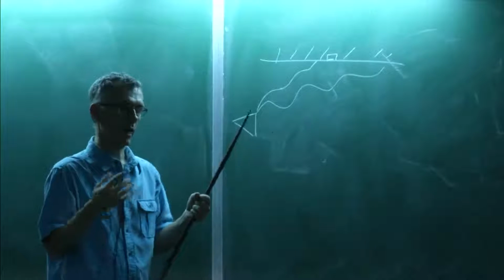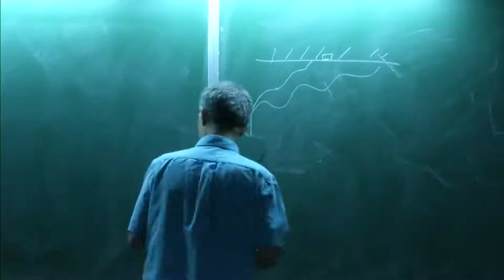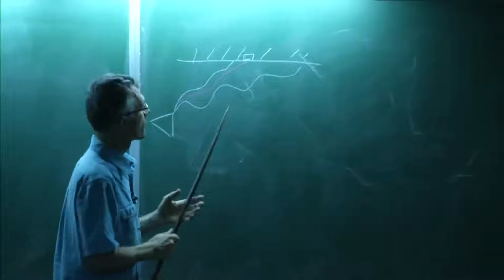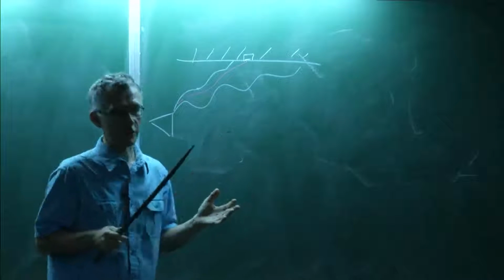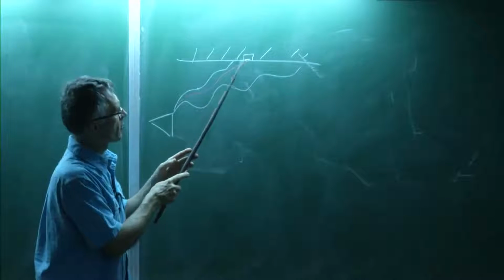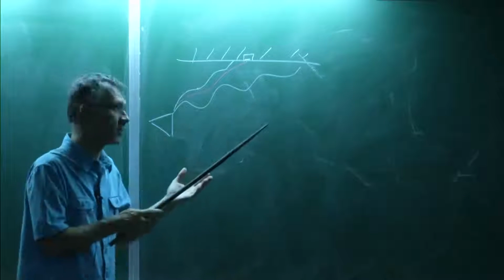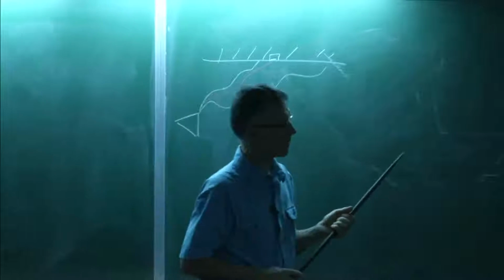So you have to handle a high temperature gas. And there is one moment which is special in the whole process. It's the moment where the flame is just on you. Okay. That's what we call flame wall interaction. That's the worst case of flame wall interaction. So when we say flame wall interaction in general, it really means interaction with cool gases, which is easy, interaction with burned gases, which is more difficult, and interaction with the reacting zone, which is really difficult.